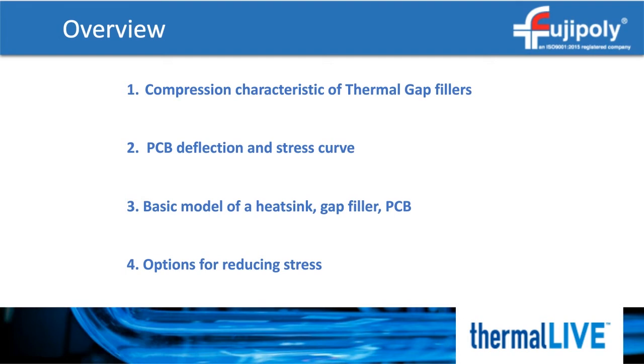One of the biggest challenges working with a thermal interface, and thermal gap filler specifically, is the stress created by compressing the thermal interface. All thermal interface materials require some pressure to work, but thermal gap fillers have a unique challenge. A thermal gap filler is designed to fill a gap that can vary due to tolerance. This means variation in compression and force. This variation in compression equates to different stresses, sometimes not enough stress, but oftentimes just not enough compression.